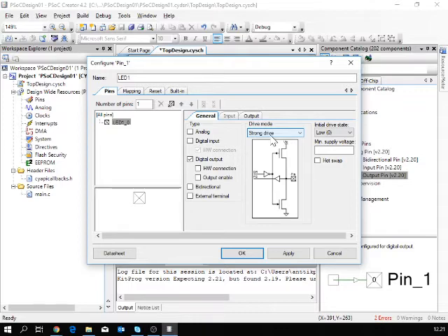Minimum supply voltage, don't worry about that. Then interesting is hot swap, meaning does it include protective diodes for hot swapping. The problem with hot swapping is the peaks that come from inductive wires. Hot swap may actually kill the device unless you protect it somehow.